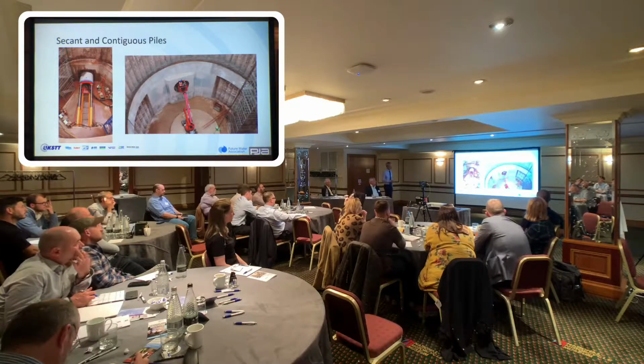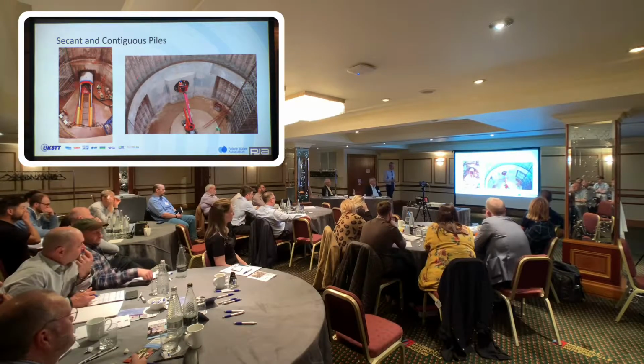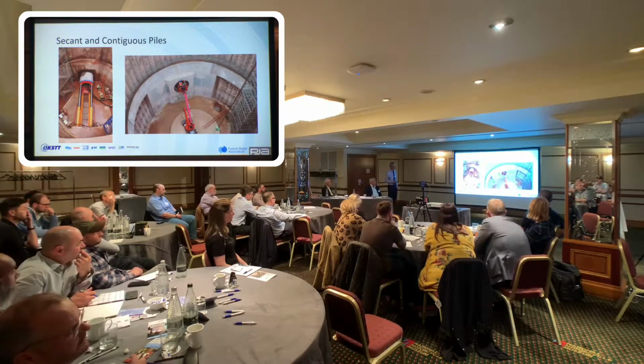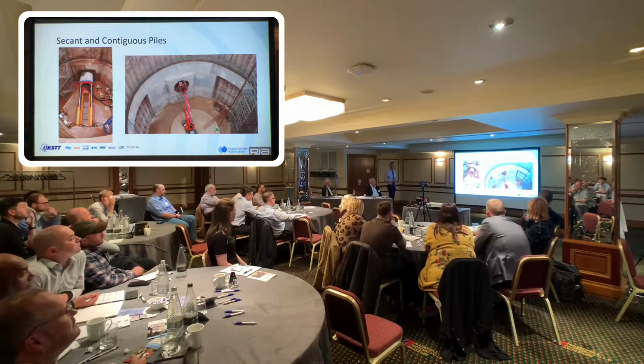So these are two pictures of the same project. This is Newark again. This is the pumping station, large pumping station shaft, which was a 20 metre diameter contiguous piled structure, and I'll tell you a little bit about why that was chosen as a method. And this is the main tunnel launch shaft, which was 12 metres in diameter, same depth.